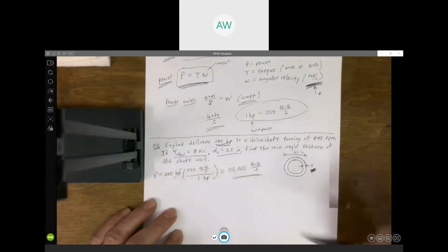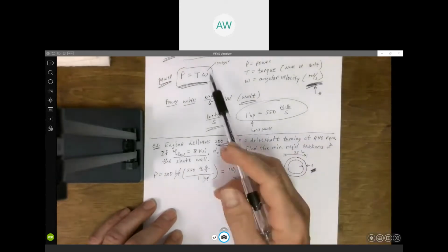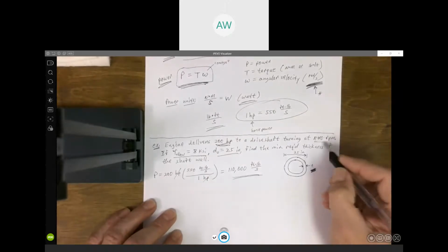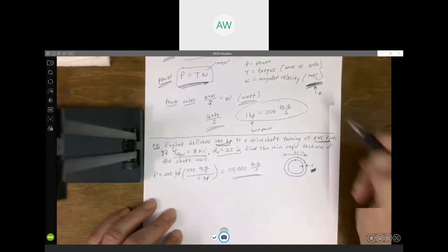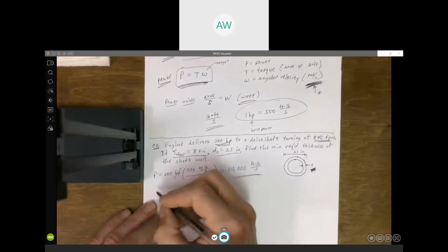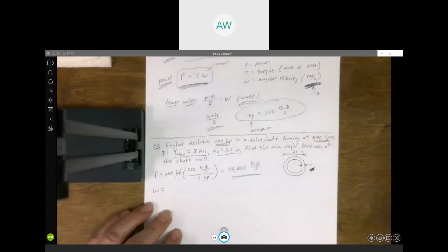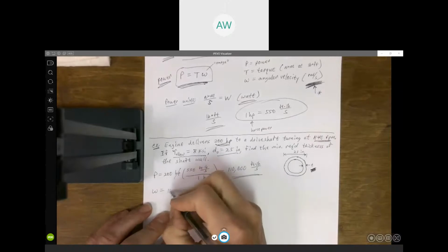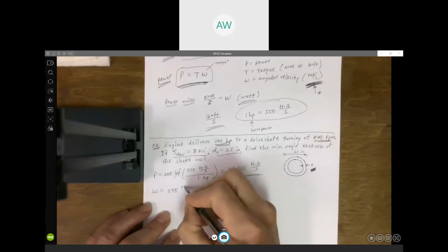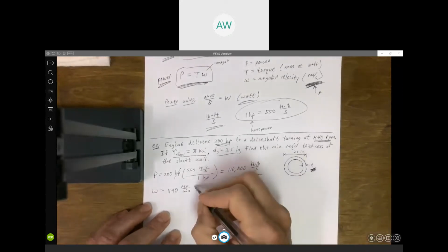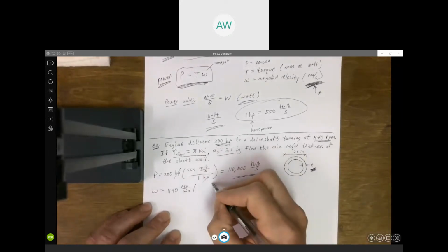And using the approach that I mentioned a minute ago, if we're going to use this formula, how fast it's spinning has to be in radians per second. So we need to get our angular velocity omega in radians per second. So 1140, those are revolutions per minute. That's what RPM stands for. And so we just have to convert that to radians per second.